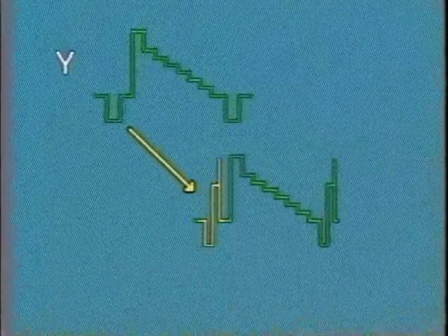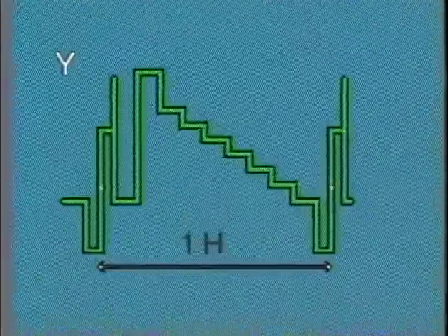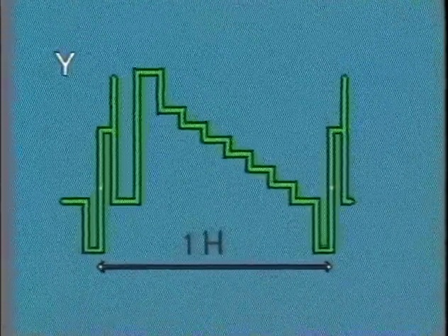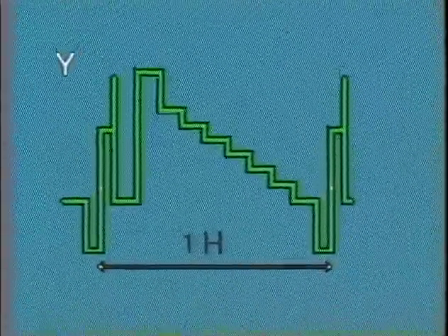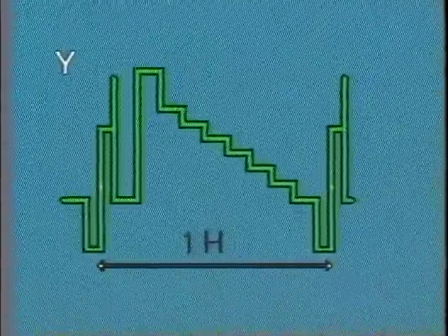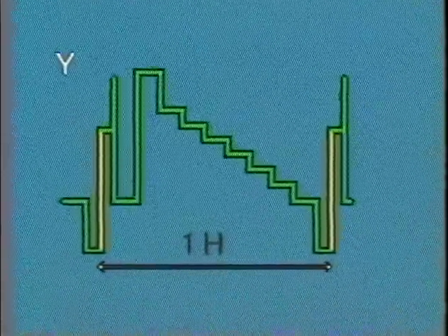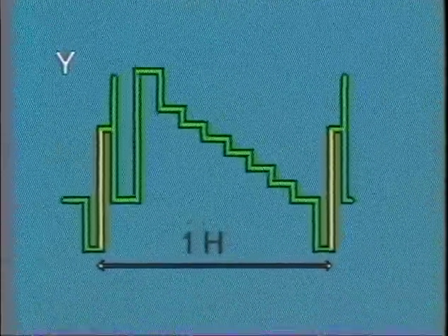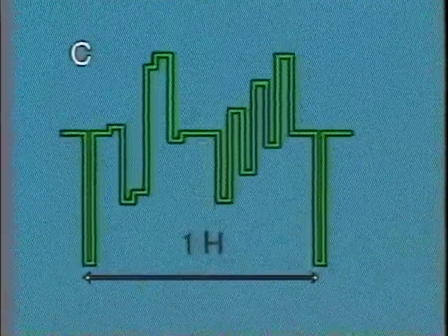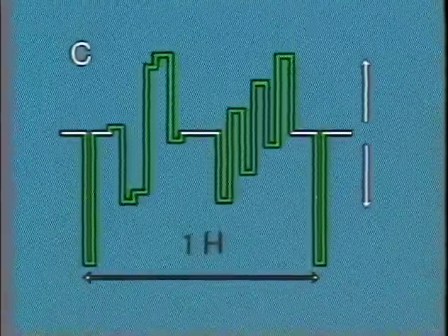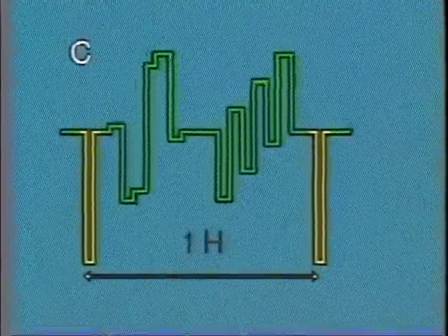This has the advantage over conventional sync as it has 0 APL. This means that each time the signal is AC coupled, there is no bounce, as the average picture level of the sync is 0. This larger sync edge will also have a better signal-to-noise characteristic. The chroma signal tends to be symmetrical about blanking level, so this large, narrow 2 microsecond sync is added.